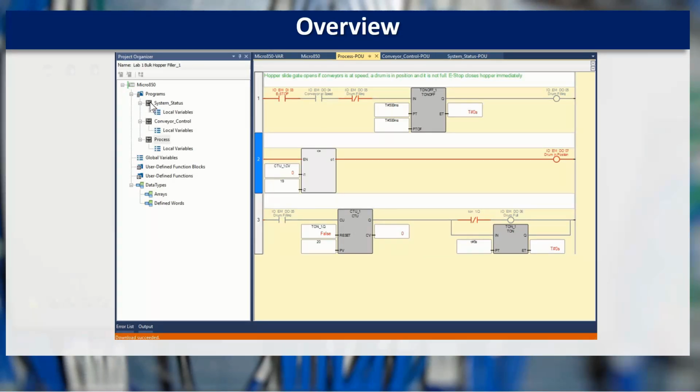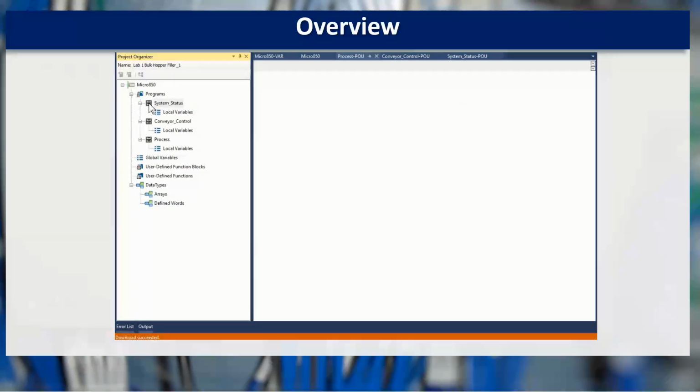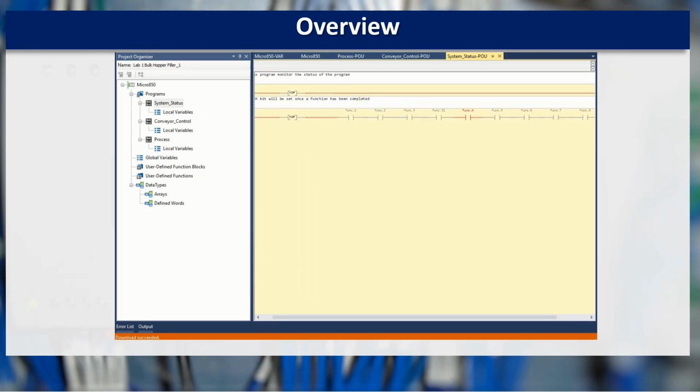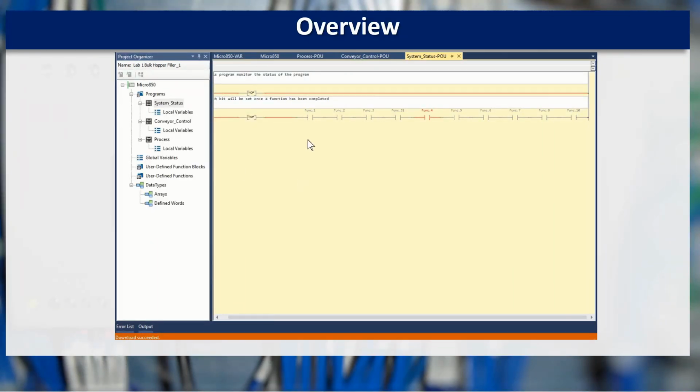I've added a program because, while I'm talking about this, I wanted to show you some of the possibilities you can use with internal variables, especially if you take a larger variable, a DINT, and use it as a construct. So I created a couple of rungs, and in the rung I made a DINT called function, or FUNC. Then I can use any of the 32 bits and name them, and follow through with the required analysis form.